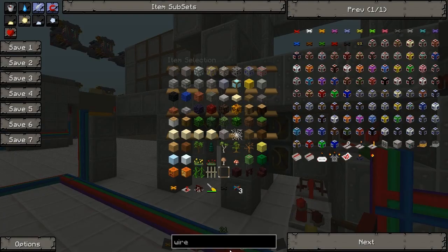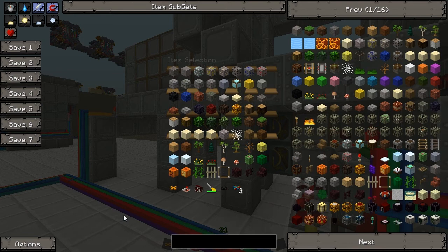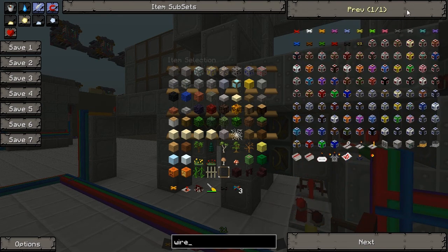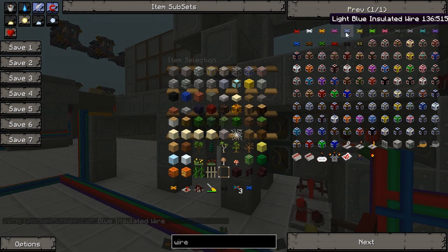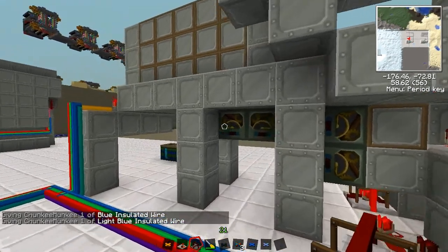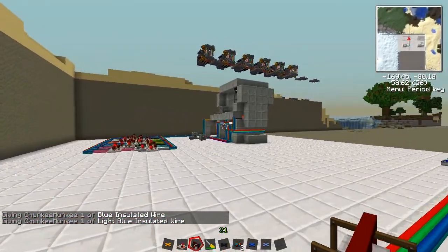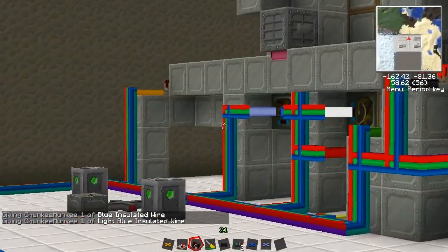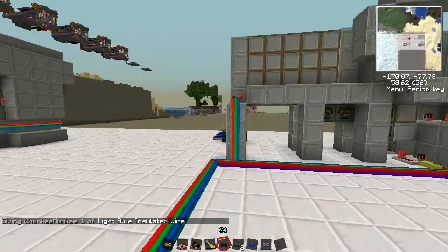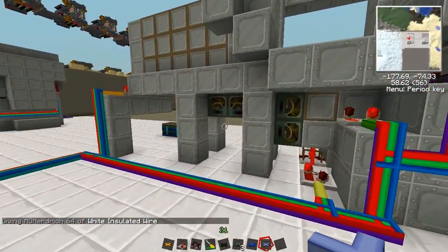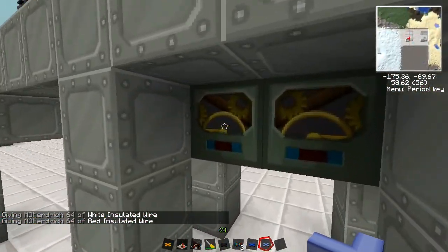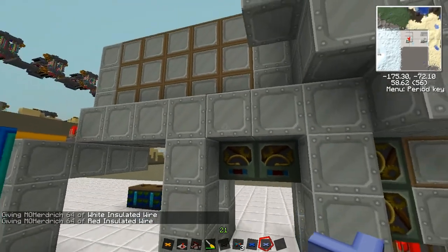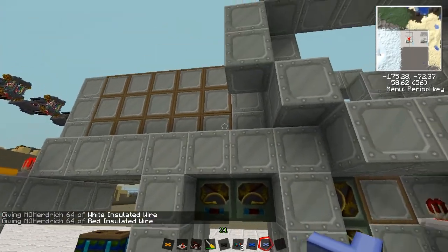Okay. So, this is rather trivial. Blue, light blue, white, and red. Okay, well I'll take the 2 blues. Blue and light blue, white, red. So let's take a little look. Yep, light blue goes on the left, which is the motor to close the door. Bearing in mind this motor is going to move the door that way.